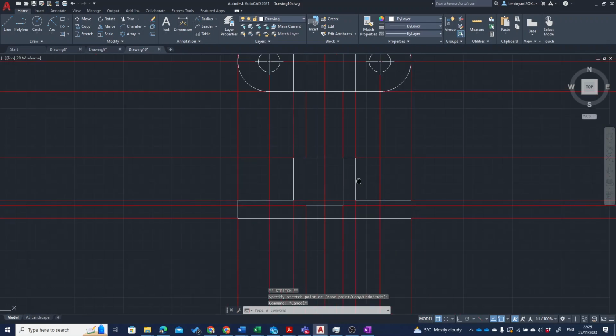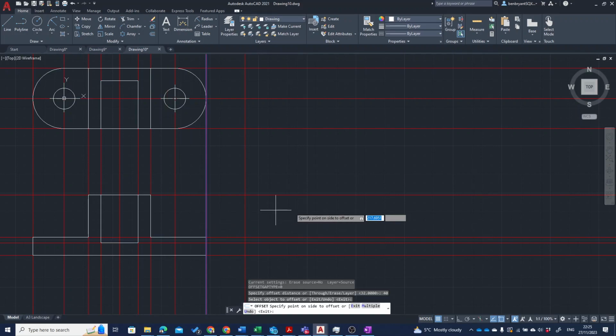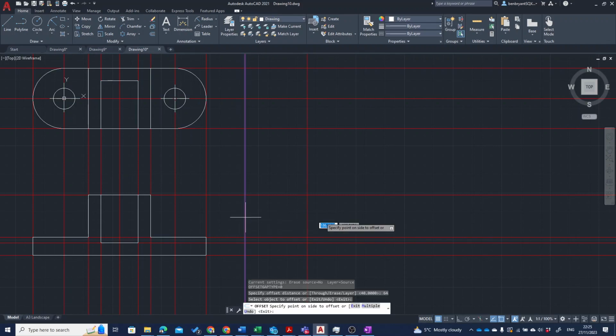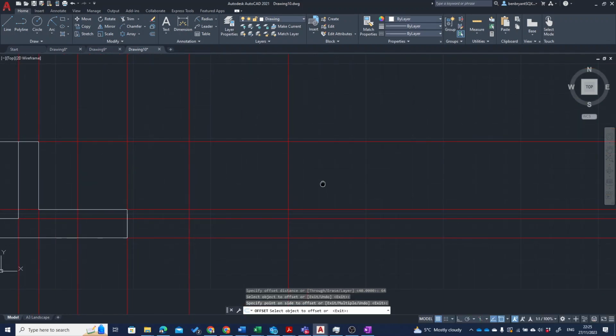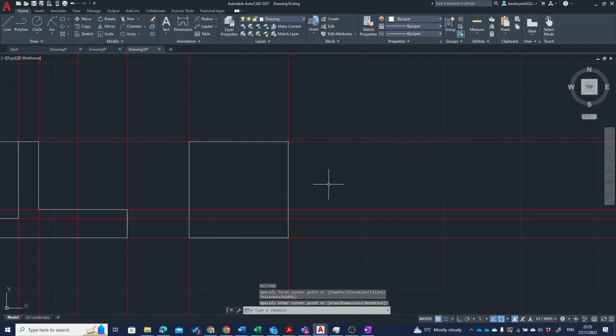Like so. So now I zoom out. Everything's lined up. Offset, we'll do 40 mil just to get away from the other offset line. Just going to do the widths now. And this is going to be 64 in length. So just 40 mil kink, 64. And again, I've got basically the same thing. So just do a rectangle from the bottom corner to the top, like so.